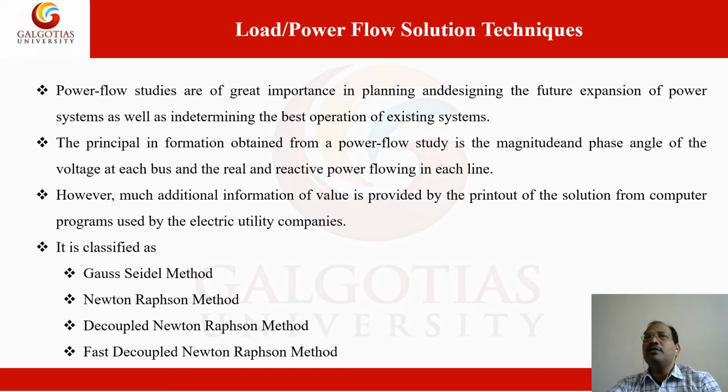Using these variables, we can calculate for each bus the active power and reactive power, the line power flow, and the line losses. But the primary thing is that we want each bus voltage phasor value, meaning magnitude as well as angle. So here we are going to apply load flow solution techniques.